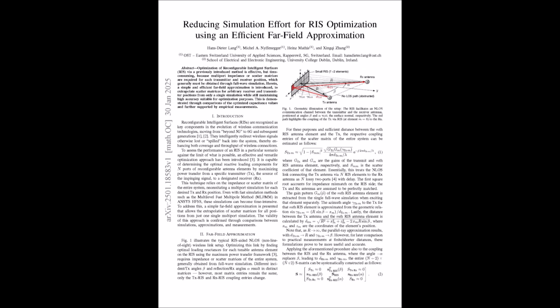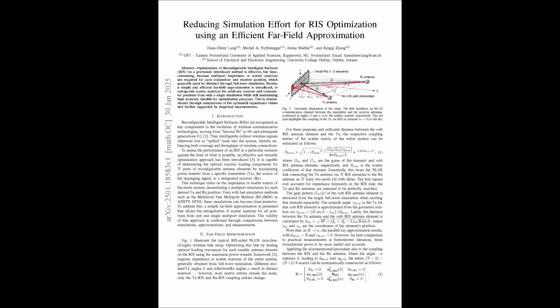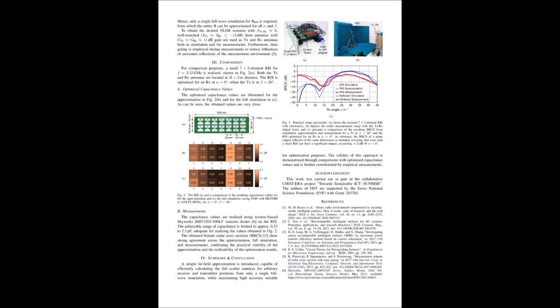And with this faster optimization method, we could tailor the RIS design to the specific geometry and characteristics of those environments. We could maximize signal strength and coverage exactly where it's needed most. So instead of just building more cell towers, which can be expensive and sometimes just not feasible, we could strategically place RIS to precisely target those coverage gaps. Precisely. It's a much more elegant and efficient solution.